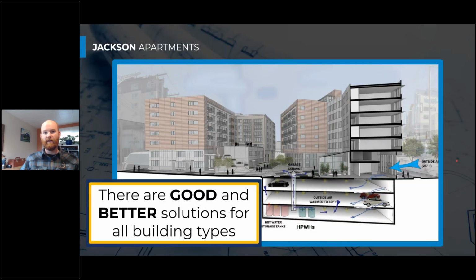And so here's that architectural rendering or image, a little bit bigger, blown up, where you can see we're drawing air in, goes through a few levels of the garage. The heat pumps are blue cylinders here, pull heat out of the air, discharge it either towards the garage exhaust fan system or directly into the garage exhaust ducting, and that makes its way outside the building.